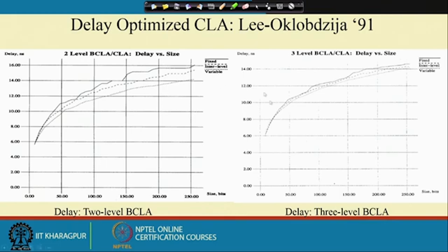Okay. So, why critical path reduction? If I consider a fan in of 9, because of the loading effect or the parasitics associated with the corresponding gate design at the transistor level, that becomes too high, which increases the delay.